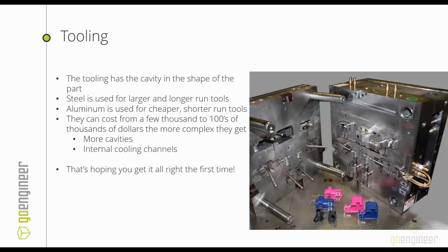And then that's not to say it has to have a very nice, smooth, high quality, high accuracy surface too, so that the parts don't get stuck on it. So if you are making cheap molds, you can make them out of aluminum, just CNC machines, subtractive manufacturing. The bigger, longer run molds are made out of steel. And you can run hundreds of thousands, millions of parts before you start seeing wear and degradation. They can wear down over time. You have to get new ones, but that's all for the very big, high production stuff.